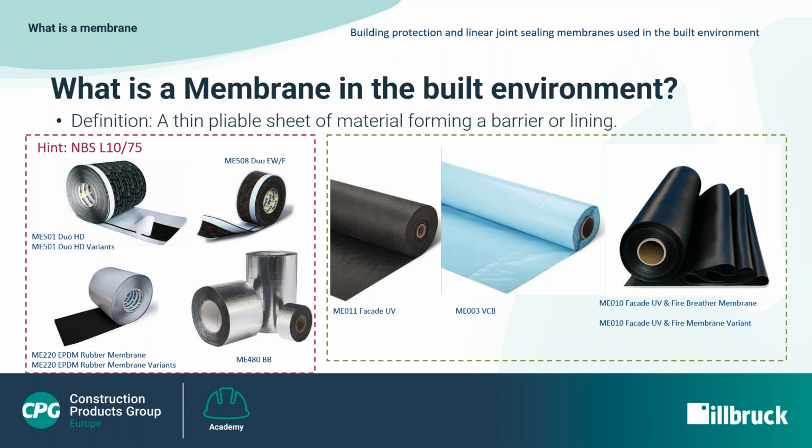Membranes are often required to provide appropriate UV resistance and always have non-degrading attributes. Once applied, membranes are left permanently in situ and should last as long as the building or the substrates to which they are applied. Some membranes are supplied as furled sheet materials on a log. All slit to size membranes start off life as a much wider log and are cut into various widths to suit different construction details.